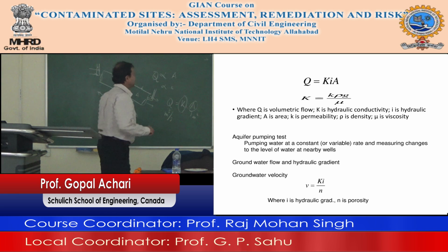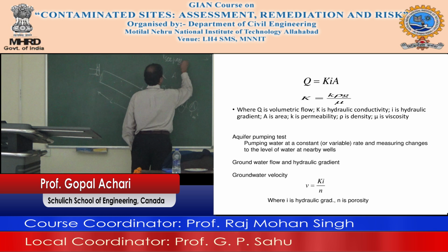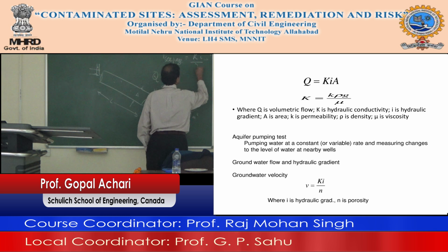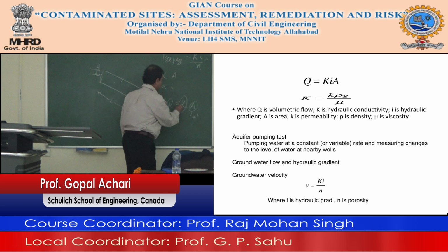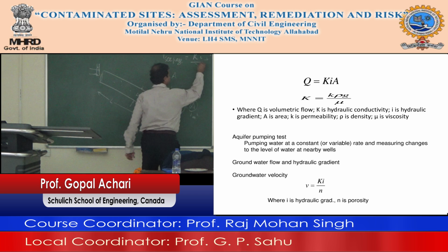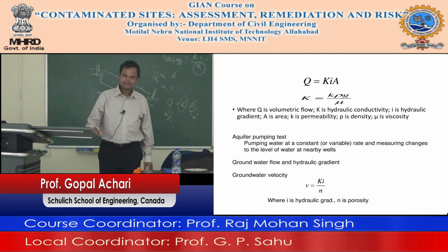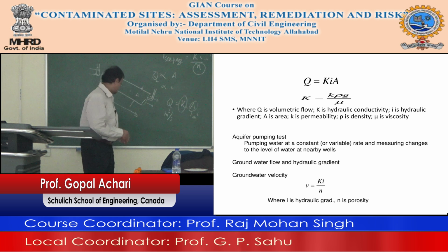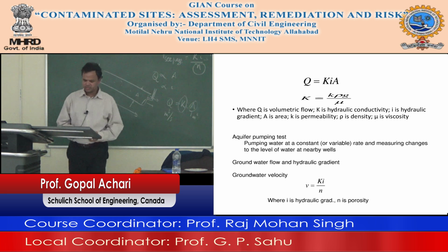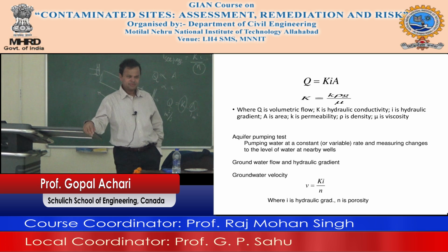So the seepage velocity, V seepage, is K I divided by N, and there is a negative sign in Darcy's equation, though not here. So next time somebody like me asks you to explain the physical form of hydraulic conductivity, you should say it's a bad question.